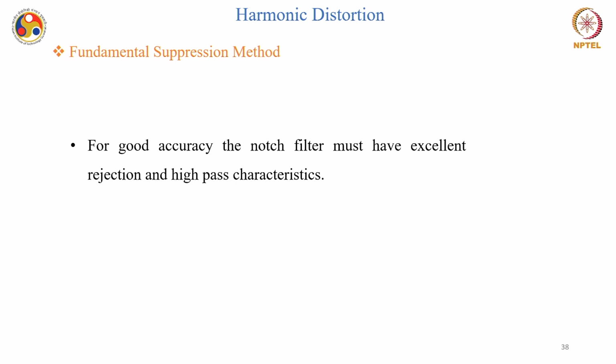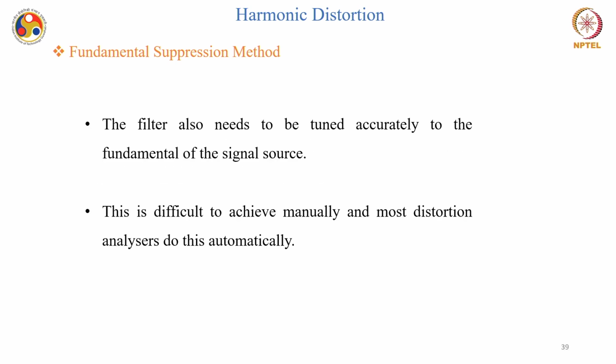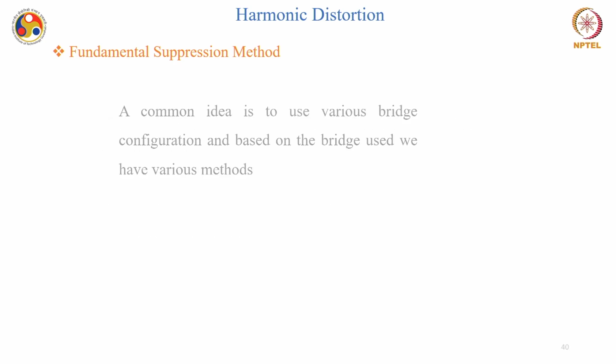For good accuracy, the notch filter must have excellent rejection and high pass characteristic. The filter also needs to be tuned accurately to the fundamental of the signal source. This is difficult to achieve manually, and most distortion analyzers do this automatically.